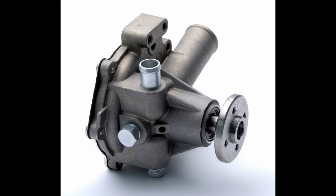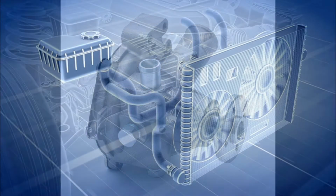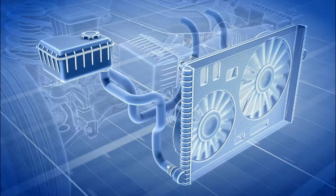When pressure in the radiator reaches 15 psi, it lifts up the spring in the pressure cap, thus opening a port for coolant to be transferred to the radiator overflow tank, thus keeping pressure in control. When coolant flowing into the overflow tank exceeds its volume limits, it flows out of the tank through the overflow hose. When pressure drops in the radiator, it creates a vacuum in the radiator, thus sucking coolant back to the radiator from the overflow tank. That's why we fill the radiator overflow tank before going out for a ride.